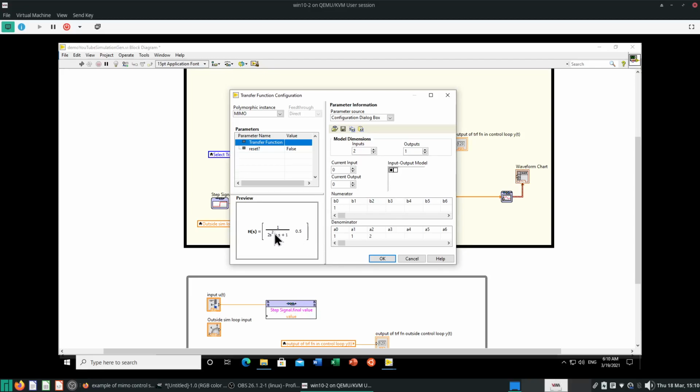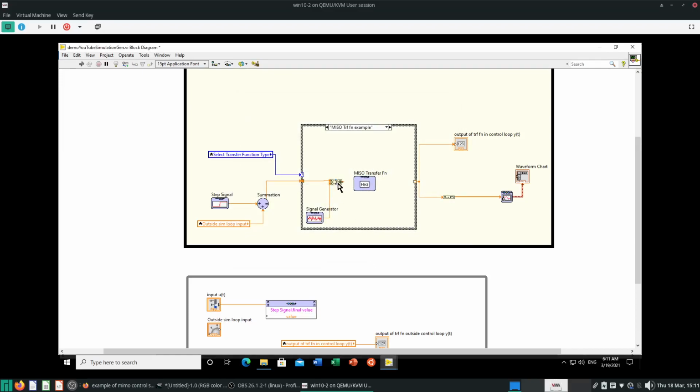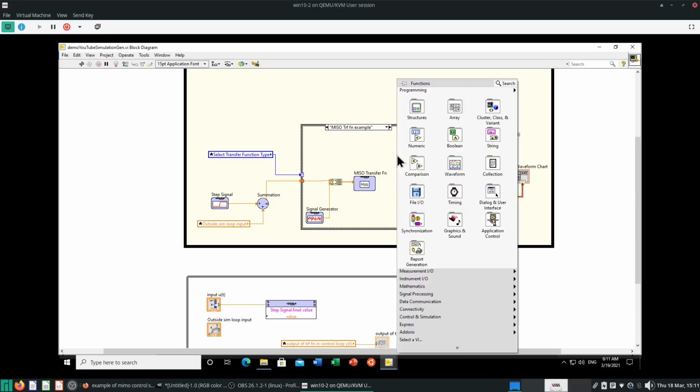The input, the one I'm controlling, is going to be this one. So once I set it up nicely, I can just wire this into the input, and of course the output, if I try to wire here, it will be broken because this output will be an array. It is not a single variable. It's not a one dimension time varying double value, numerical value.